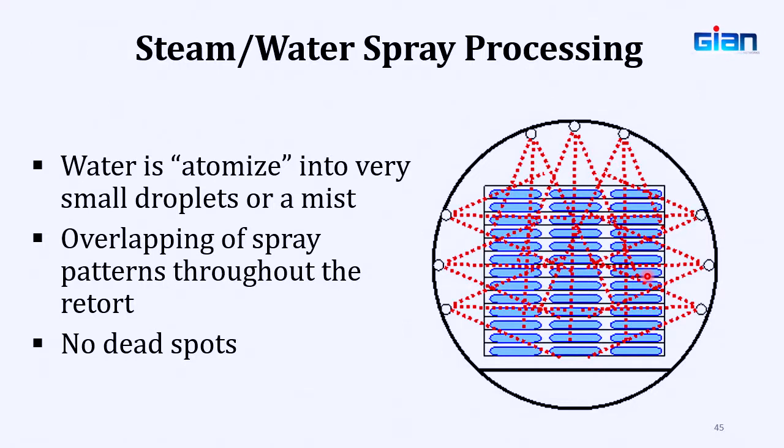So what we normally would do is put the thermocouple in this pouch or tray and collect the heat penetration data for this. And we'll make sure, okay, if this pouch or tray is sterilized, then all others are also sterilized. That time overexposure will be there in the outer periphery. Correct. So there will be some exposure. That is true in any retort. When you have a large number of cans in a big vessel, from one end to another end, top to bottom, there will never be complete uniformity. But that's a limitation, and you can consider it.